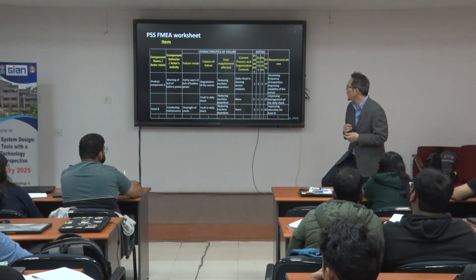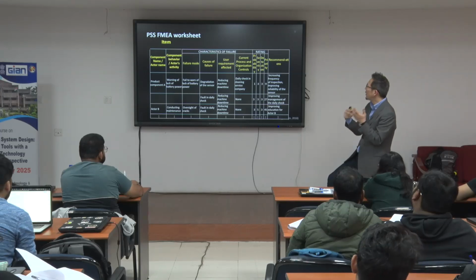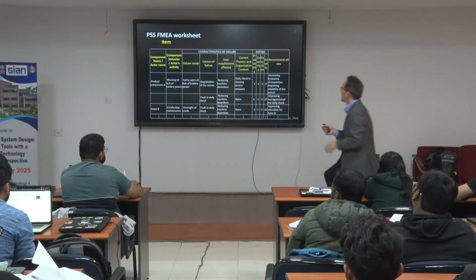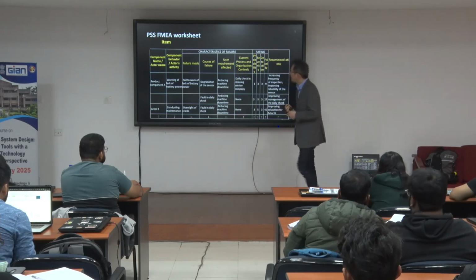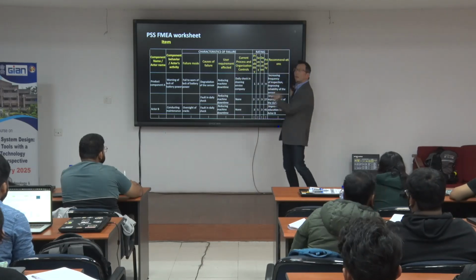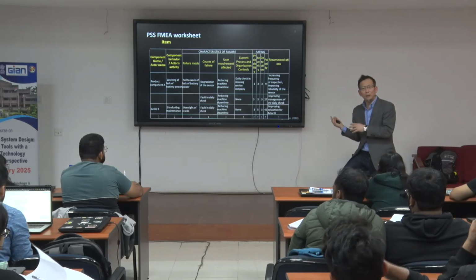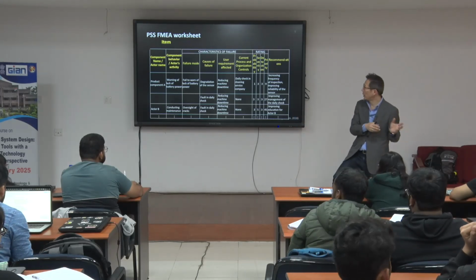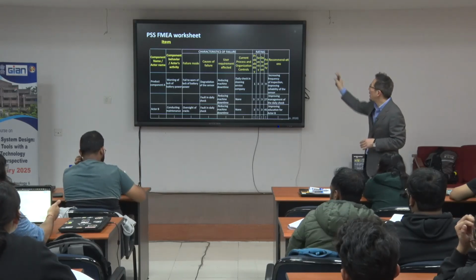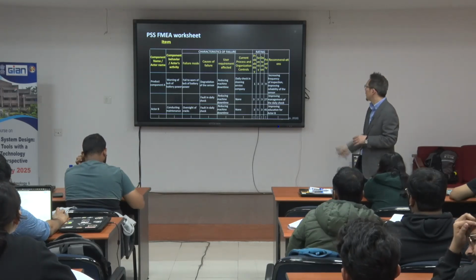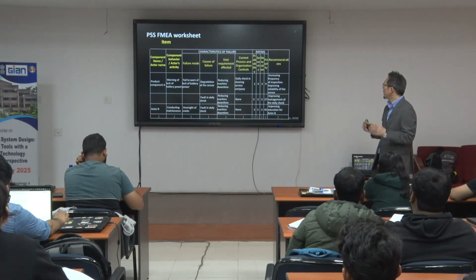Let's say in this case, warning of lack of battery power. So that's an expected product behavior. And then failure happens and it fails to warn of the lack of battery power. And then thereafter, the same description is applied as in the case of product FMEA. So the only difference compared with product FMEA lies in the first two columns. And everything else can be applied in the same way.